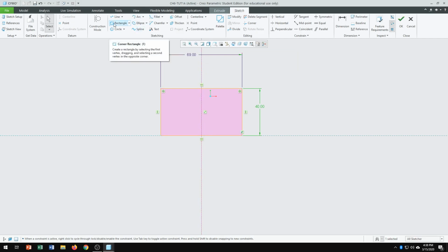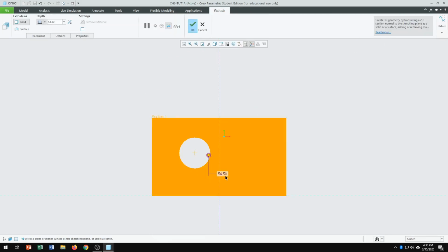Okay, all right, so let's quickly create a circle in here, and automatically you see that this dimension is going to pop up, which is 8, a light blue dimension. We call it 18, and this dimension, the diameter of the circle, double click on it, and you don't have to erase it, you just type 16 on top of it. And then this one here, we say that's a 22. Okay, 22. Those are the measurements or dimensions, and you have to be very careful how to enter the dimensions, and it should position the circle with respect to the x-axis and the y-axis. All right, everything is good to go. And then we're going to give a depth of 10.